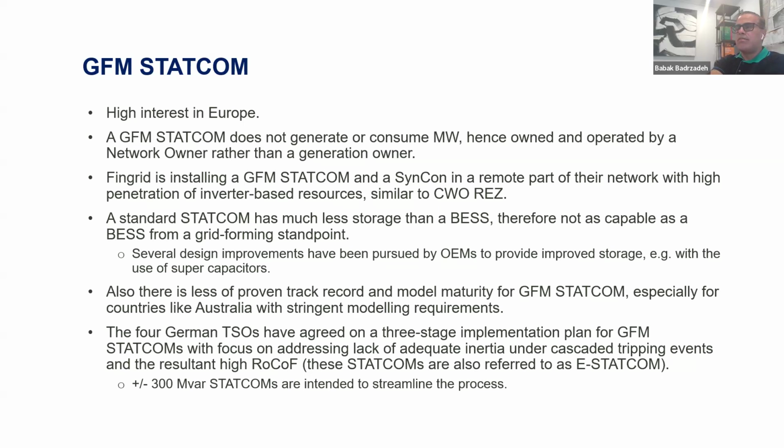And to provide some other examples, in Europe this is becoming extremely popular, especially among the four German TSOs that are installing GFM STATCOMs, or what they call E-STATCOM. This is intended to address the perceived decline of inertia and increase in rate of change of frequency as the synchronous generators are being retired in the power system. And that's all. I pause here.